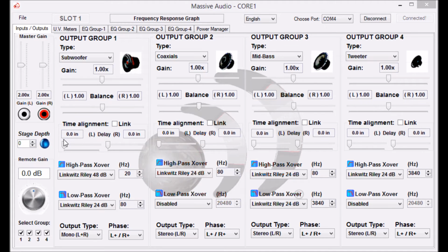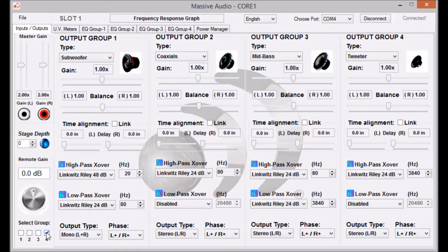Before adjusting the gain of your speakers, it's good practice to deactivate the external remote control, avoiding confusion. Set all output groups to 0. Begin by adjusting your mid-bass speakers because the range of frequency reproduction is right in the middle of the audible band, so that should be your first reference. Then proceed by setting the gain of your tweeters to match the mid-bass speakers.